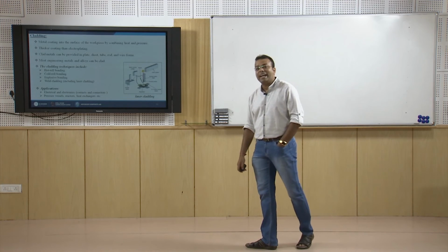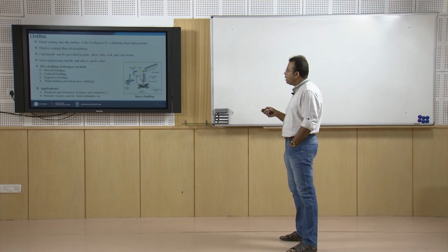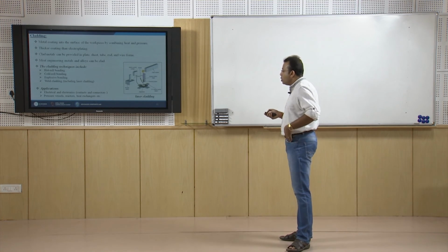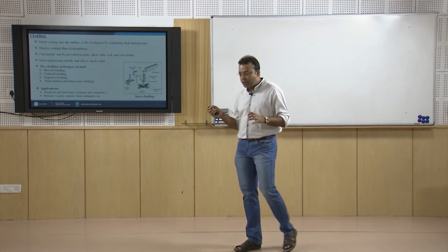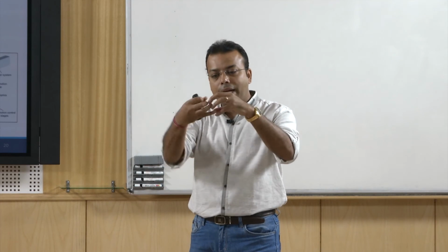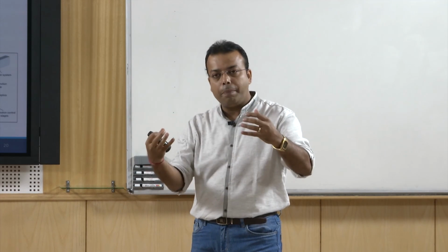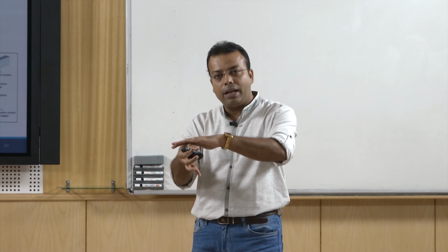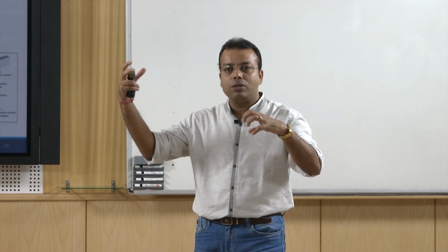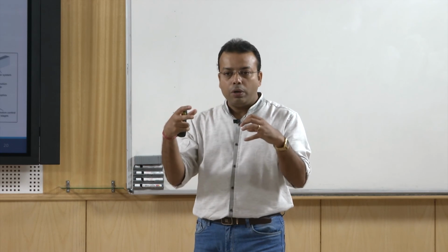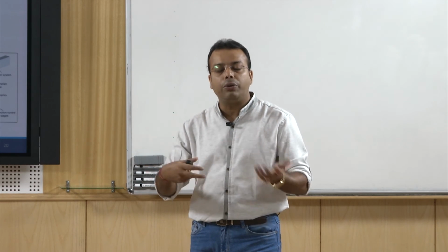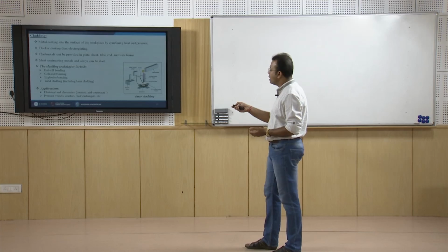Next one is called cladding. Cladding means metal coating onto the surface of the workpiece by combining heat and pressure. Till now in laser alloying, we have seen that we use certain kinds of particles, and using the laser beam to heat them, the powder material becomes liquid and makes a layer onto your top surface. But here, simultaneously, we are giving heat as well as pressure. So, we perform these operations under heated, pressurized conditions. That is why it is known as cladding.